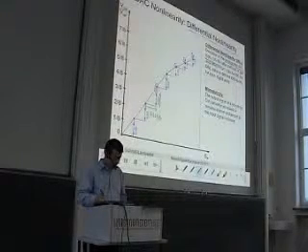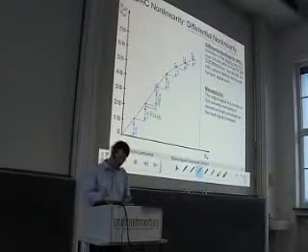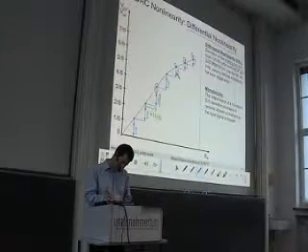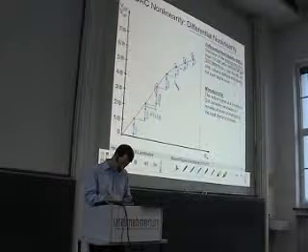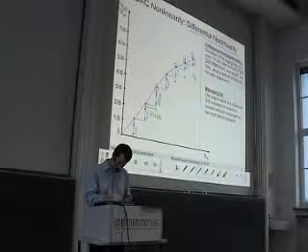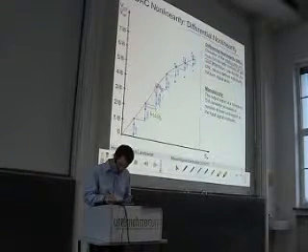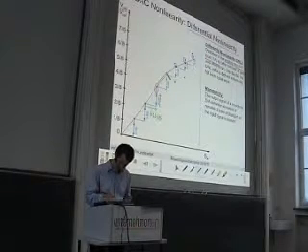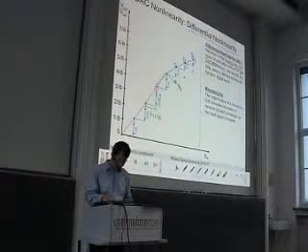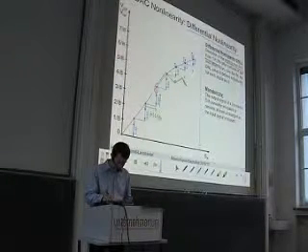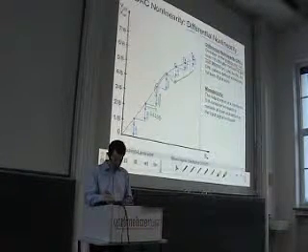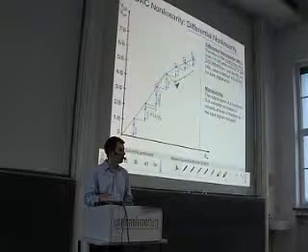An example of non-monotonic behavior would be that we go from this point to the next one, and instead of going up, we actually go down. And then perhaps up again and up again. Then our characteristics would look like this. We go up here, we increase the input, and then we go down, which should not be the case in an ideal converter. And then we go up and go up again. So in this region, we have a non-monotonic behavior.